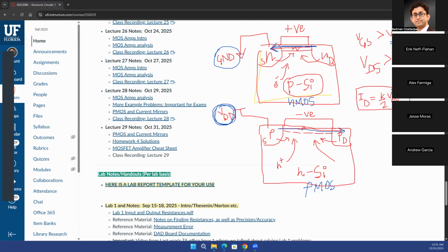As a circuit engineer, we are very much comfortable in looking at voltages and currents. And then we defined our threshold voltage. Remember that when you plotted your VGS versus ID curve, your gate to source voltage versus the drain current curve, it looks like this, similar to a diode as well. And we defined that, okay, after some point, my current increases exponentially, and I defined that point as my threshold voltage. So that's from a circuit designer's point of view. A device engineer will define the threshold voltage as that much amount of gate voltage that you need to apply so that your channel becomes as much N-type as it was P-type before for the NMOS.